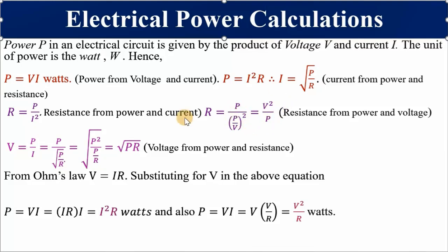So your result is, when you are given voltage and power, you can calculate resistance. You can also calculate voltage from power and resistance. If you follow the mathematics, it means that voltage is equal to the square root of power times resistance. Hence, my statement, you must give this slide the respect it is due, because it is so important. We have looked at the one formula for calculating power and derived the rest.